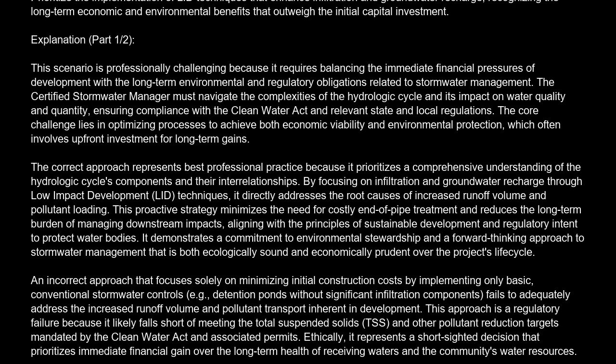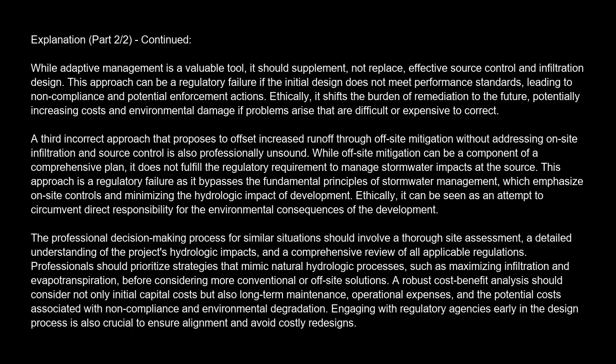community's water resources. Another incorrect approach that relies heavily on post-construction monitoring and adaptive management as the primary strategy, without robust pre-construction design for infiltration, is also problematic. While adaptive management is a valuable tool, it should supplement, not replace, effective source control and infiltration design. This approach can be a regulatory failure if the initial design does not meet performance standards, leading to noncompliance and potential enforcement actions. Ethically, it shifts the burden of remediation to the future, potentially increasing costs and environmental damage if problems arise that are difficult or expensive to correct.